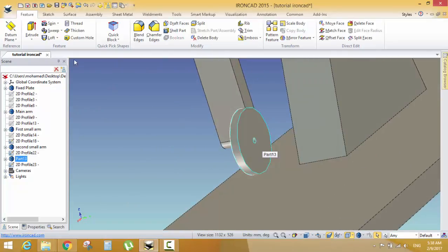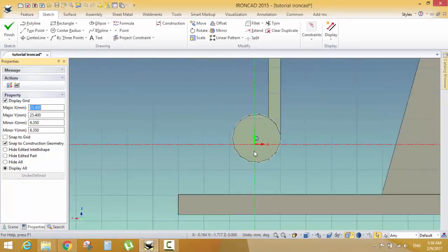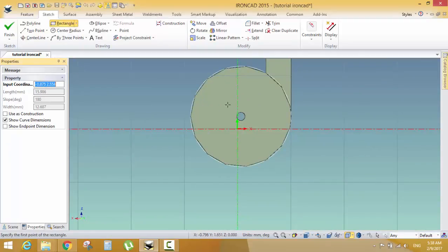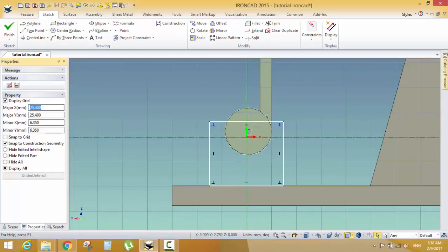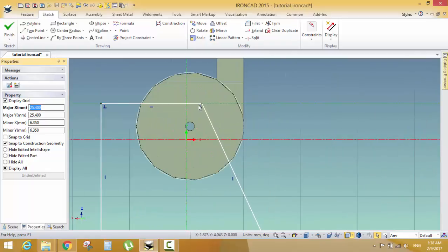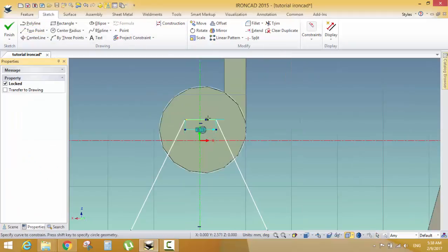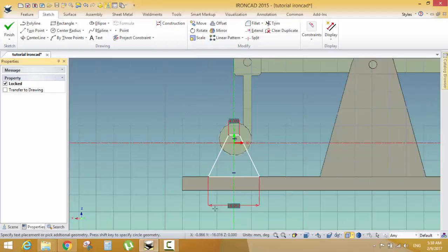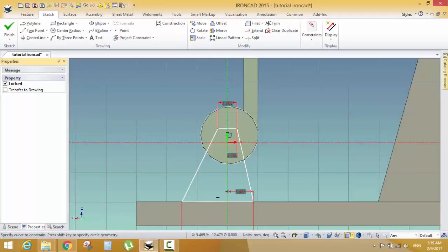Let's create the stand. Okay, let's select this face, sketch 2D shape. Select this face. Okay, great. Now let's create a rectangle like this one. And now let's modify its shape. Have this point to this point, and this point to this point. Now let's give it some dimensions. Say this will be 4, and this will be 15, for example, and 2, and 7.5, for example.